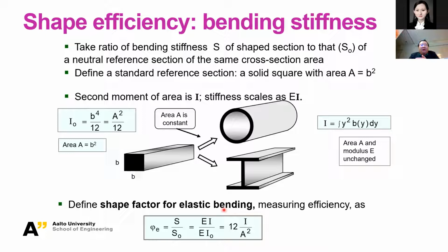The bending stiffness can be related to the E modulus of your material and the second moment of the area, which is this I. From task 1, you learned how to calculate this, either by looking at the book, or with a systematic mathematical derivation. Both will be okay, and the main message is for you to learn how to get this second moment of the area. They will differ a little bit, but not significantly.